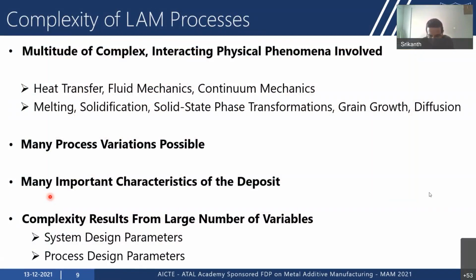So you have conduction into the substrate, convection, radiation. There's fluid flow within the molten pool, convective fluid flow. You have melting taking place, the powder particles melting, the powder wire. Then you have solidification, solid state transformations, grain growth, diffusion. All of these physical phenomena are happening simultaneously, resulting in an extremely complex process.